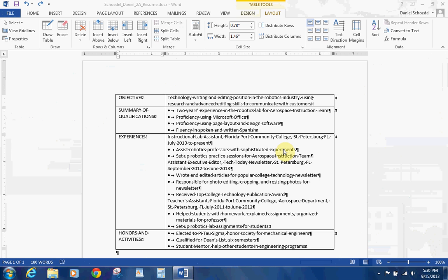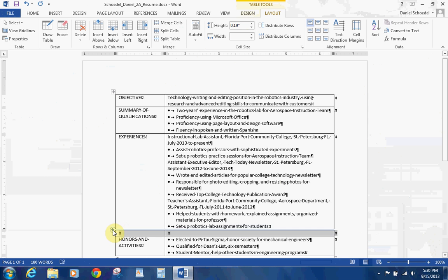Okay, the next part of the lesson over on page 186 talks about using the one-click row column insertion to modify the table dimensions. Basically what we want to do is put a row between this area and this area. So put your cursor right here, click down on the line here. See how this arrow pops up? If I click on this arrow, all of a sudden a new row appears. Sometimes it's a little simpler to go up here and use these options as well. It's kind of a personal preference, however you like to do it.